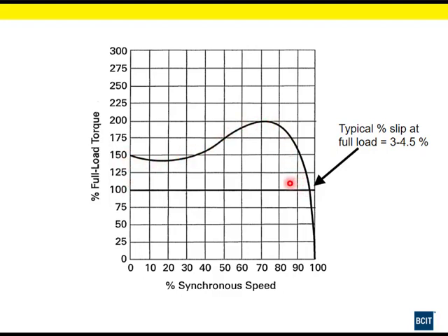Now this is just this one type of design. With different rotor designs, which I'm going to look at in another video, this starting point here is going to be a little different, and then the curve here is going to be a little different. So here we have our starting torque, which is about 150% at 0 RPM. As it accelerates, we have our power factor reducing.